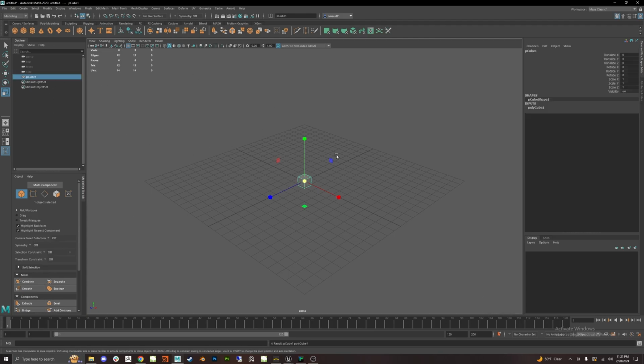And if I create that cube again, and I am currently in my move tool, if I hover over this and I see that it is my move tool, and I see that there's a W, I can hit W and it automatically switches, and now I can move my object. If I hit Control Z, you can see in the bottom right hand corner, it goes back to where it was. So those are my move tools.